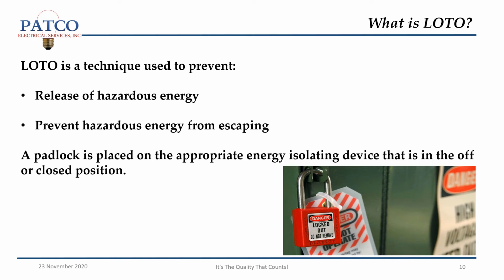Lockout tagout. Lockout tagout is a technique used to prevent hazardous energy from escaping. A padlock is placed on the appropriate energy isolating device that is in the off or closed position.